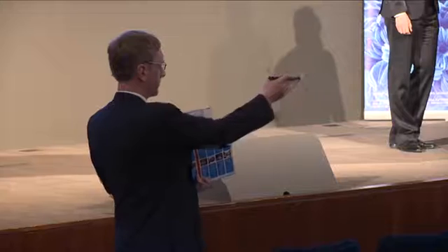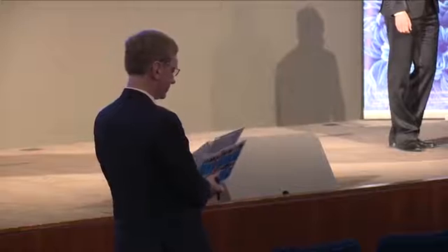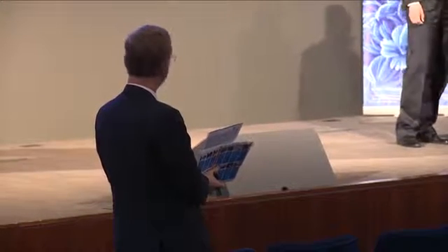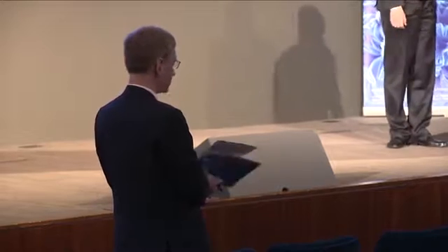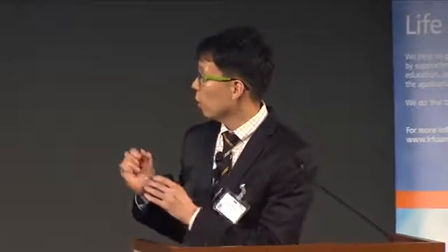Questions, please. Hi, I have a question about the flexibility of the hull structure. How much does it affect the actual resistance in terms of increase or decrease? And should we do something about it? That depends on the flexibility of the structure. In our case, I changed the flexibility of the shape. Near the resonance region, it is increased. In the region where wavelength is similar to ship length, hogging and sagging happen, and in this region, the added resistance decreases.